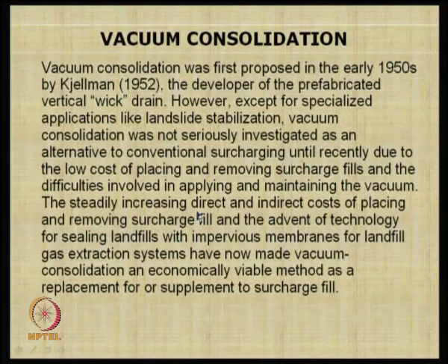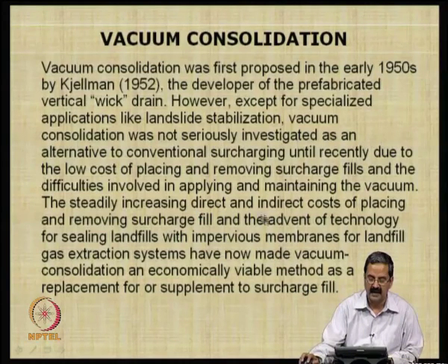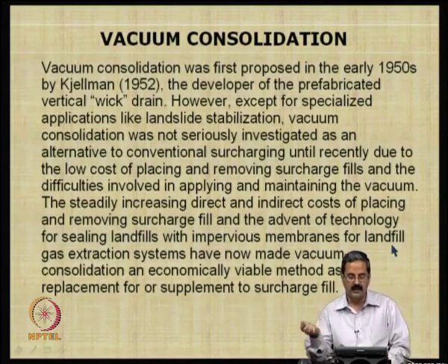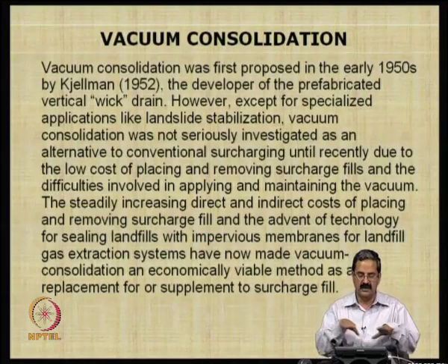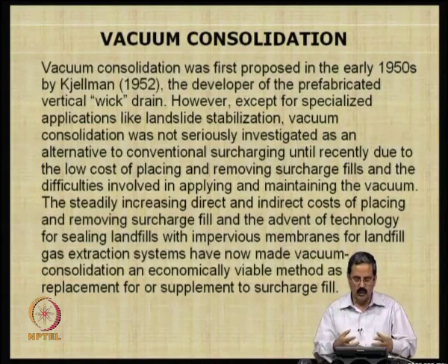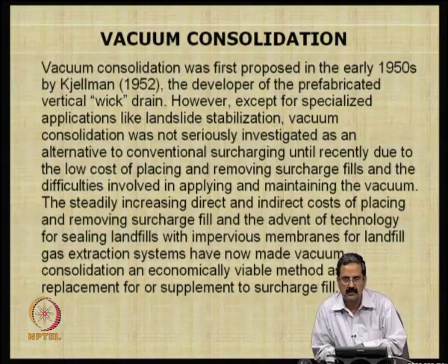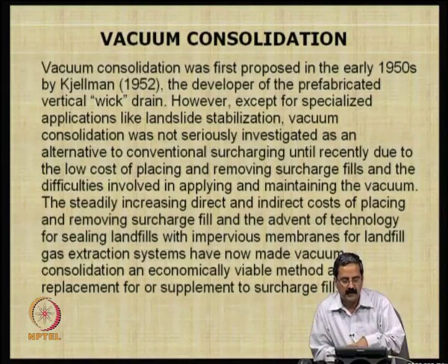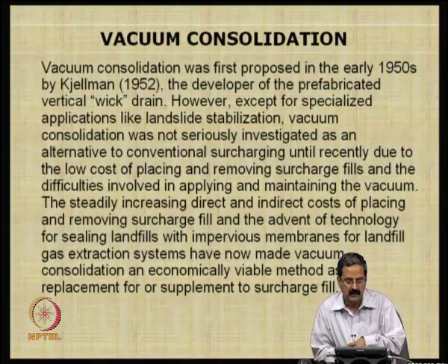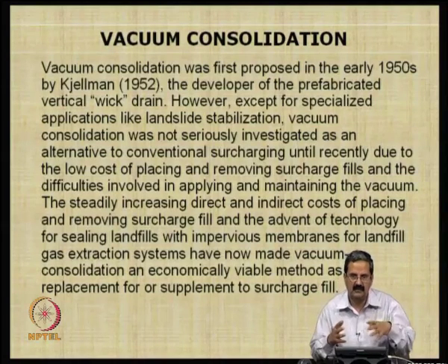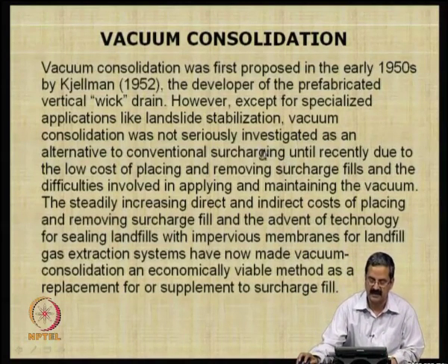But the situation now is somewhat different. The direct and indirect costs of placing and removing surcharge are high, and there is the advantage of sealing landfills with impervious membranes. Vacuum technology has also improved, and the cost of the fill that you have to place for surcharge was also very expensive.